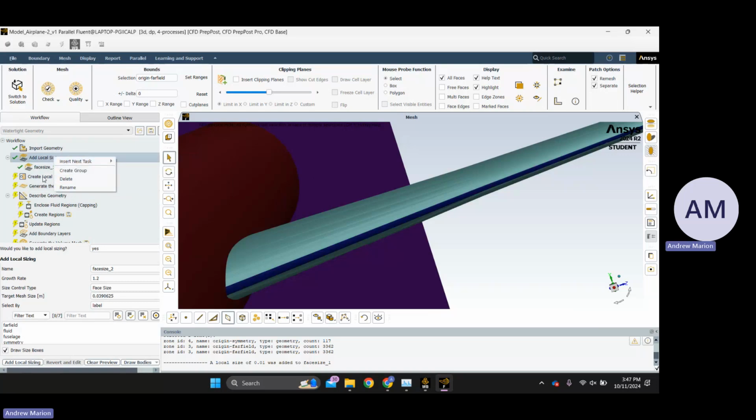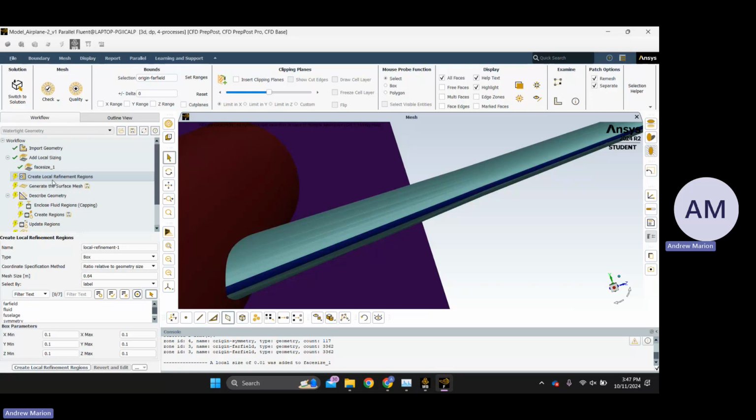And then you get this down here, which says generate local refinement regions, and this is where we'll define our region. Right, where was that? The local refinement region, right below face size. Okay, yeah, there you go. It's in the same region. So right below face size we have local refinement region, and then you have your name. We can leave that. Try slowing down your mouse movements a little bit. It's lagging on here, so it might be hard for them to see.